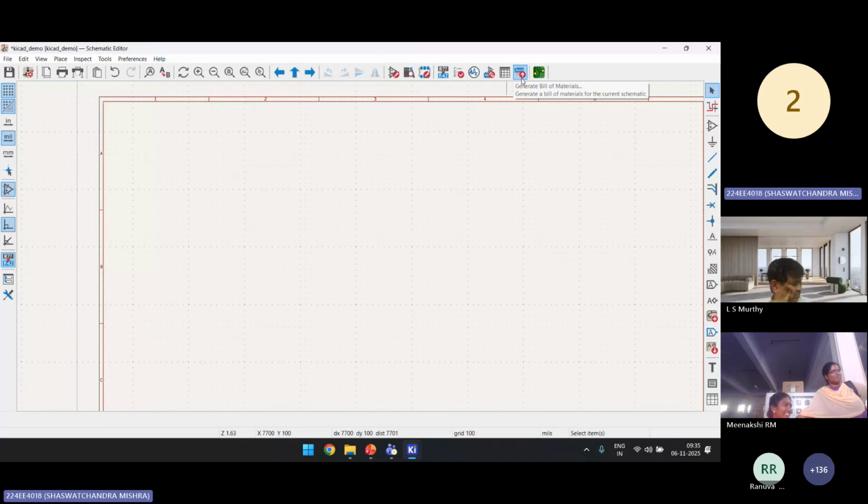purchase them. Okay. Next is the PCB editor. From here, you can go to the PCB editor page. Okay. So this comprises of all this. Then from here you can print our circuit, and here you can see there are three options. There is inches, there are mils, and there is millimeters. I suggest you stick to mils, and the grid should be 100. Okay, you can change them, but I suggest you stick to 100 for this specific circuit. Okay, so that's enough for this introduction.